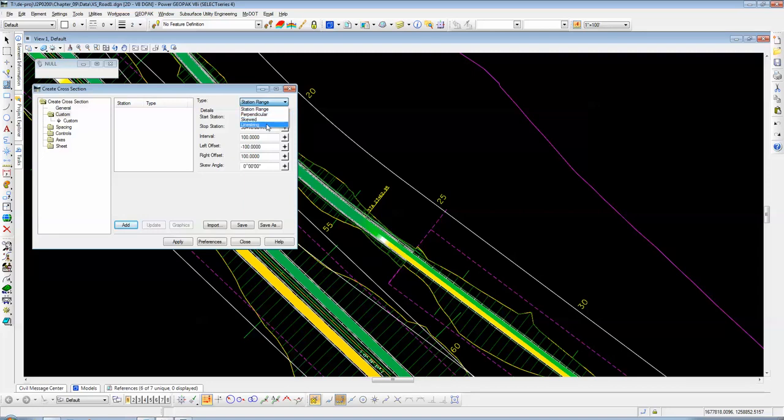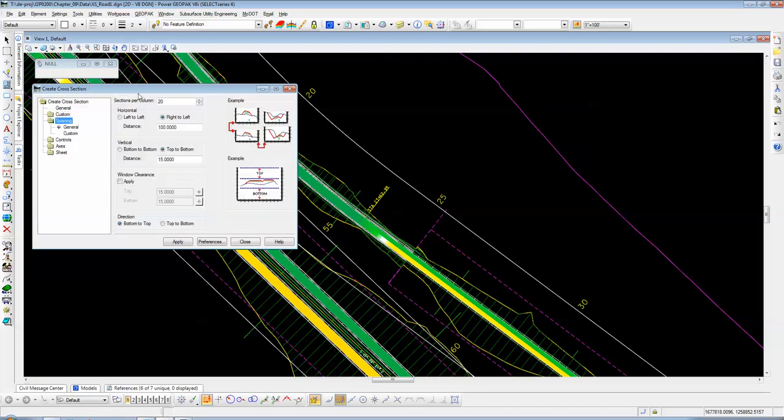We got a pattern shape or patterns file out there that you can actually put a line string in and follow that line string if you choose this. Okay, and when you choose those different options, you get your start and stops, and you get your intervals and your left and rights, whatever you want to set up on this. Okay, and since these are more custom type selections, it leaves the user to do about anything he wants to do, or she. The next leaf is spacing.